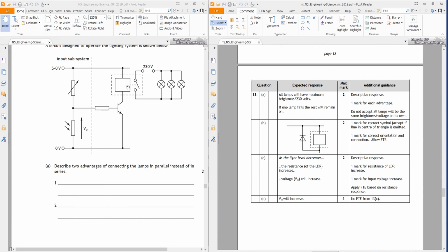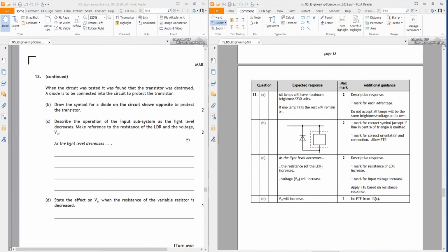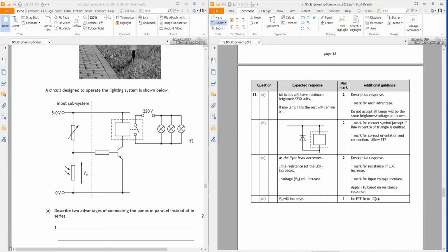When the relay switch is off, there'll be a big voltage generated and it'll blow up the transistor. You need to have a diode across the relay to protect the transistor. The transistor is the fragile component. That resistor is protecting the transistor. You could adjust this down to 0. Now put 5 volts onto the base, and that would damage the transistor as well.